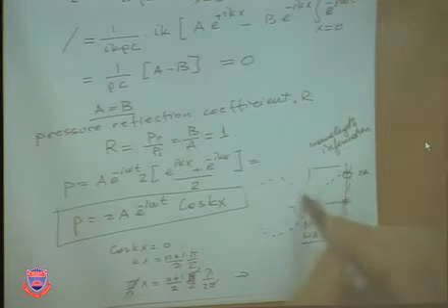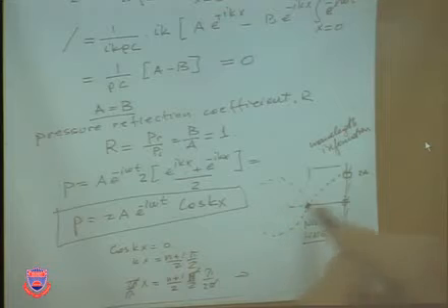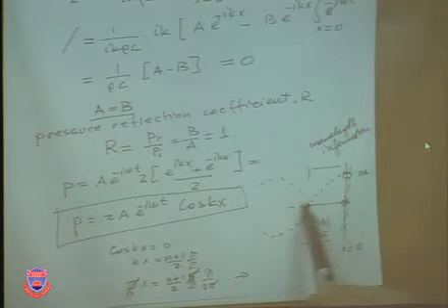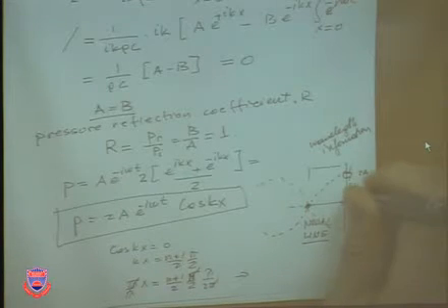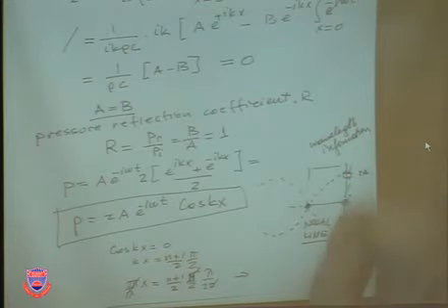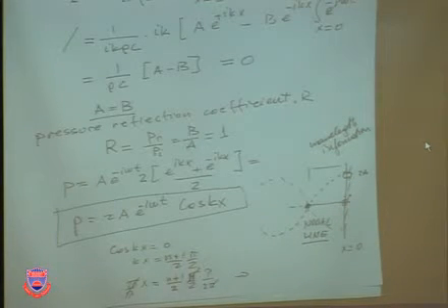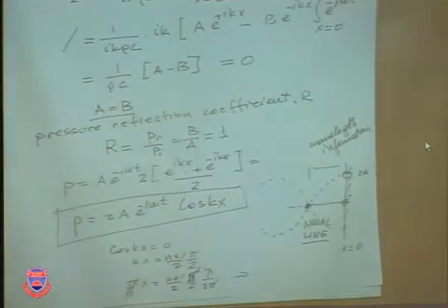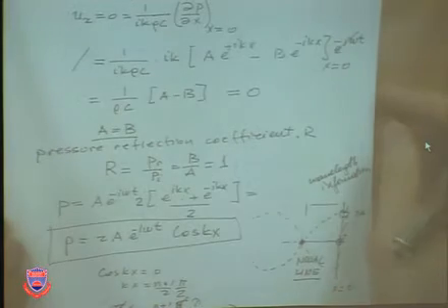And by making these measurements as you go away, and I will get to it, so again, don't write it yet, by making these sound pressure measurements, you can actually determine the impedance properties of materials. That's why we're now looking at these extreme and simple cases, and we'll build up to more complicated cases as to how you can, just by measuring sound pressure changes, understand the material properties of the surfaces.